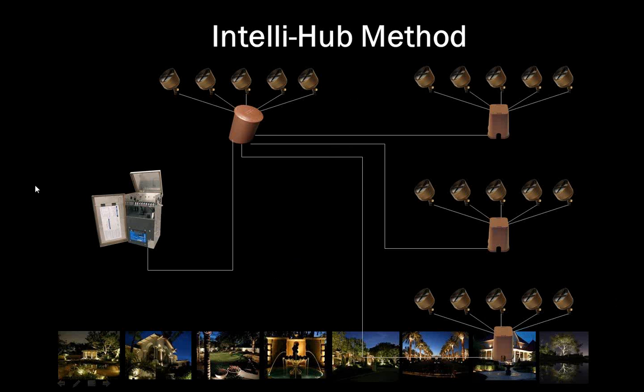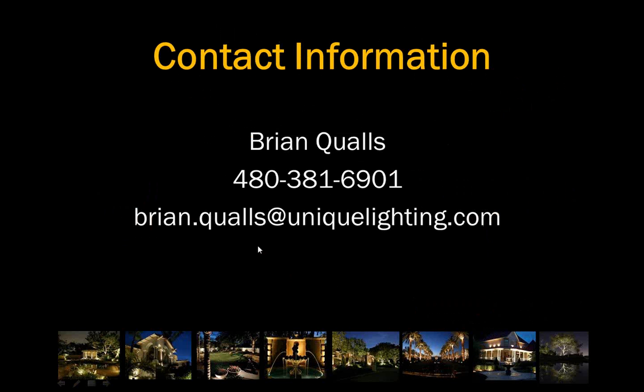Now this system only works on LED. If you try to do it on a halogen system, you'll be disappointed and never get the voltage drop to work. It'll just be too great coming out of this hub.